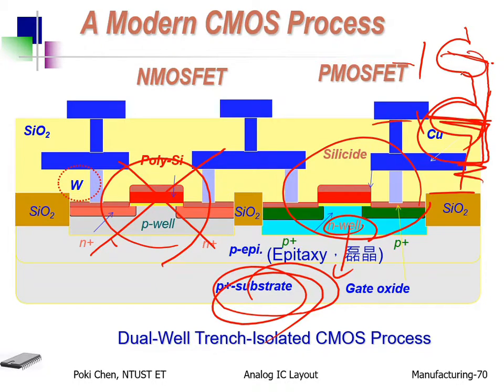If you connect it to its source, then this source is connected to the body, but all the bodies are the same. So this one is shorted out. Its source is to the ground, its body is connected to this source, and this source is also connected to the ground. So it is not functional at all. Sorry for that.